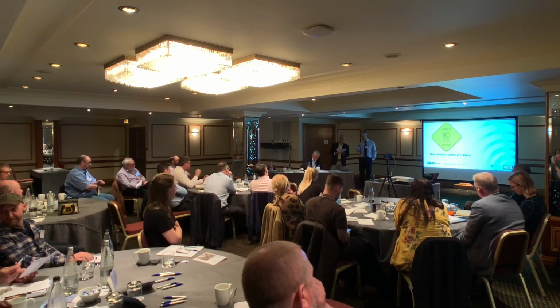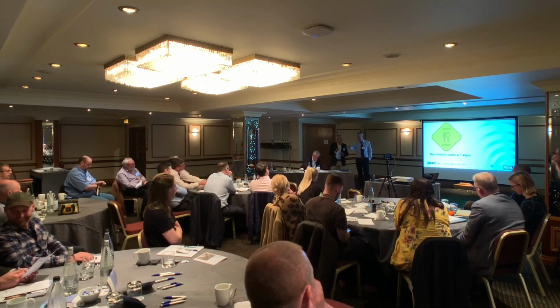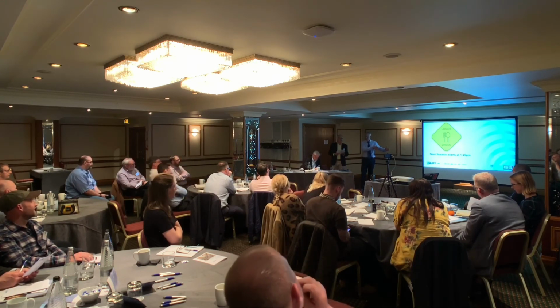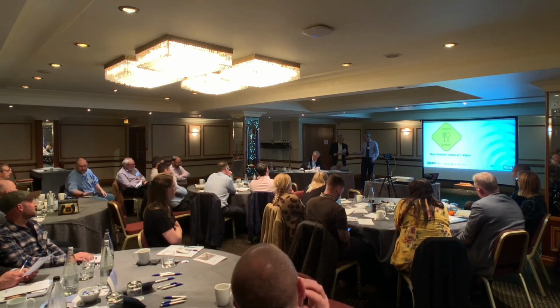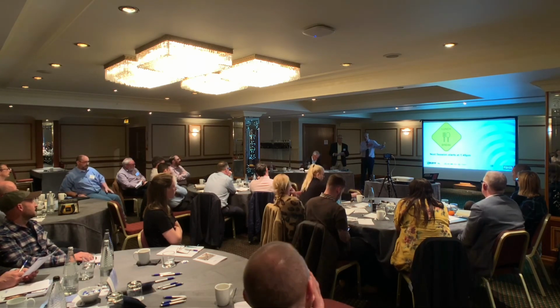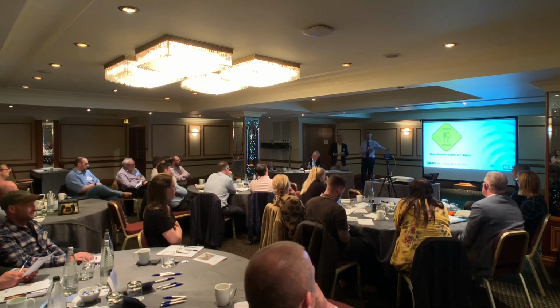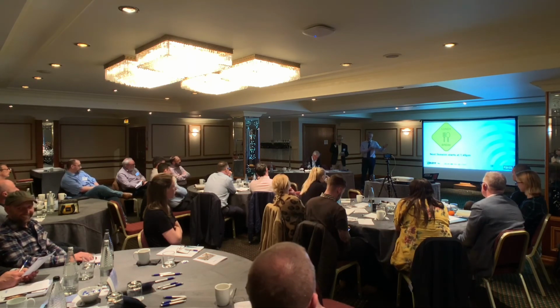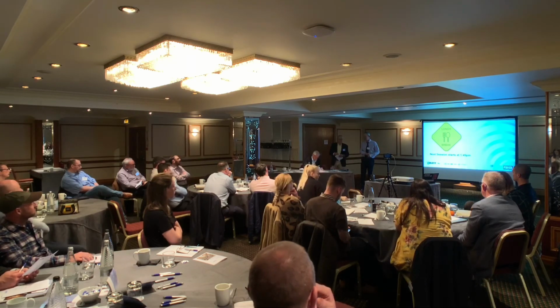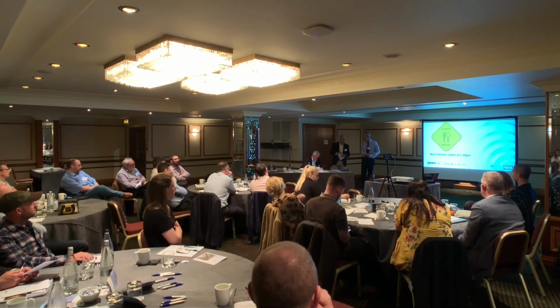I guess I should have said that the machine is really important, but the separation plant is as important. And personnel-wise, you're quite right. On a tunnelling scheme, we would have a mud engineer on the plant, and his job is to maintain the slurry in the right consistency, which is very similar to drilling. In fact, most of them come from a drilling background.